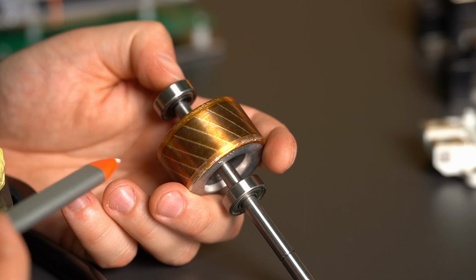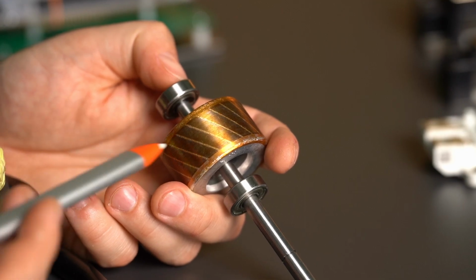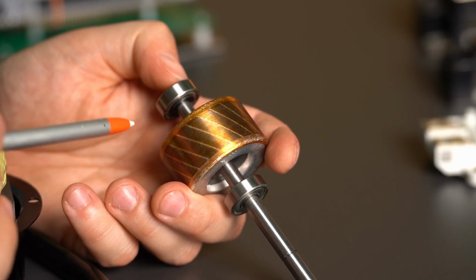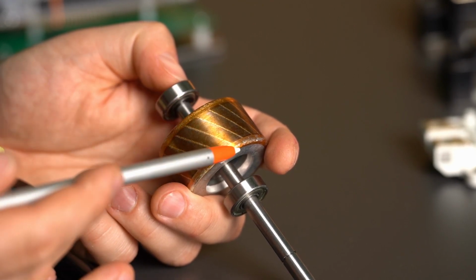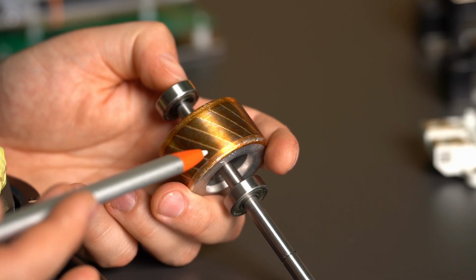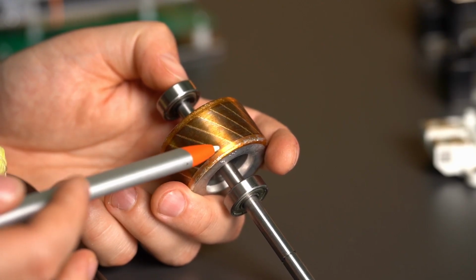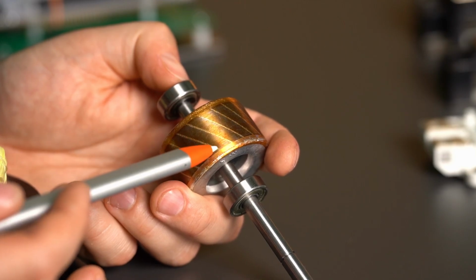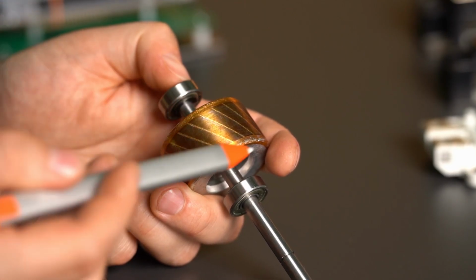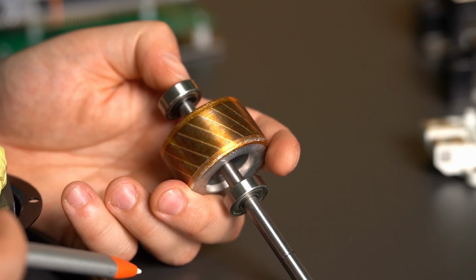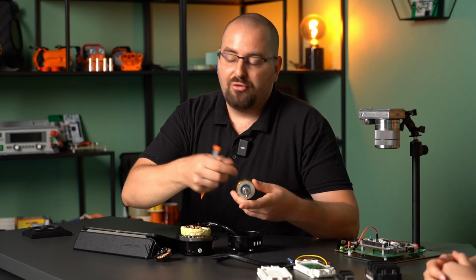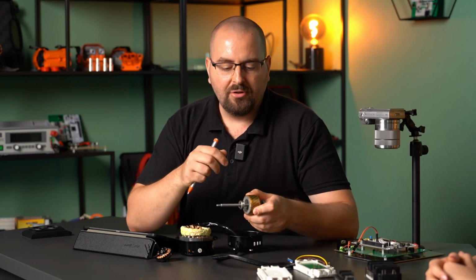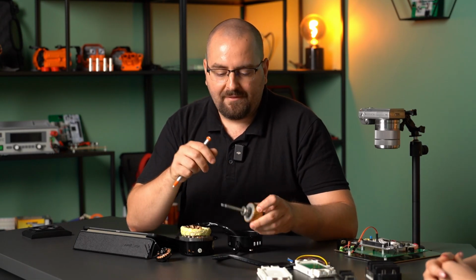So these grooved iron plates are put together, put into a mold, and the whole thing is cast with aluminum. Basically, the iron plate itself is designed so that the aluminum flows into the grooves and they become the conducting rods that basically form this rotating winding. And finally, there's a ring of aluminum on both sides. And that basically short circuits these aluminum rods. So, it's the same type of squirrel cage design rotor we've shown in the picture, but it's much easier to manufacture.